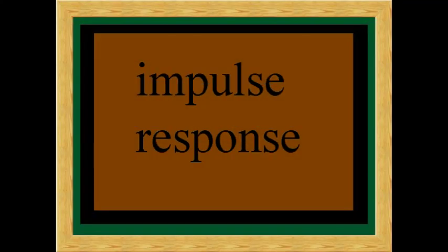Impulse response is the most straightforward way to implement a digital filter by convolving the input signal. All possible linear filters can be made in this manner. When the impulse response is used in this way, filter designers give it a special name, the filter kernel.